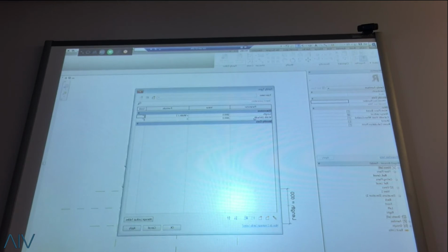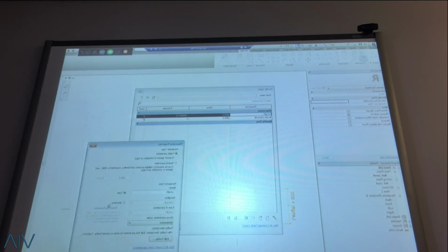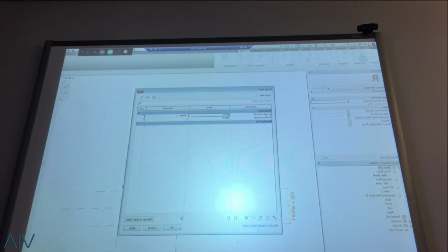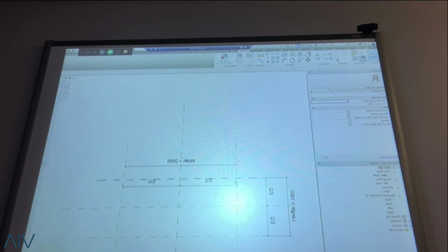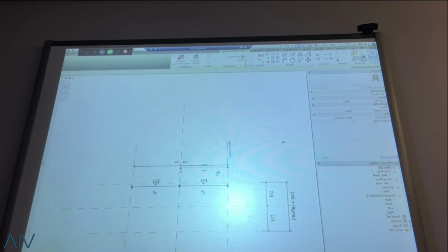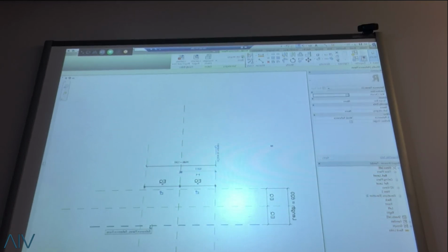Right now it says no, I cannot do it, because I forgot to change this to an instance parameter. An instance parameter will only work with an instance parameter, but sometimes you can make it work. An instance parameter will always display that default value, that parentheses default, which means it's an instance parameter. So I'm just going to say OK, and now it works. Now if I stretch this, to flex the muscle, it does it for me. Great job. That's how you slowly build your family.